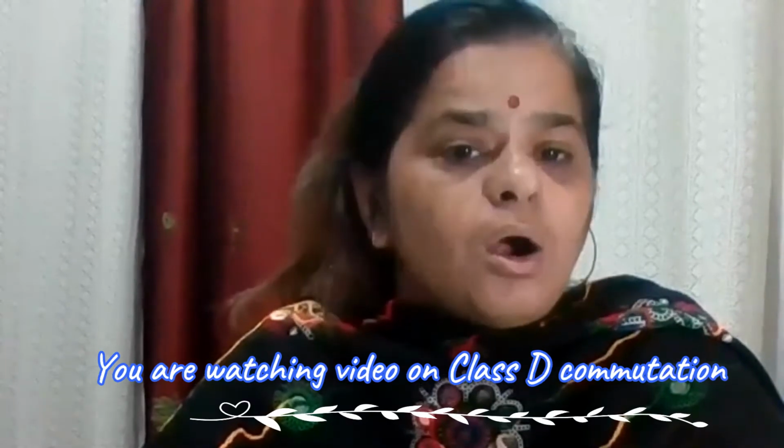There are two kinds of commutation methods available. One is called natural commutation and the second one is called forced commutation. Natural commutation can only occur when the connected supply to the silicon control rectifier is of AC type, because AC by nature passes through zero two times in one complete cycle. So when it completes its positive cycle and goes to the negative cycle, in between it passes through zero.